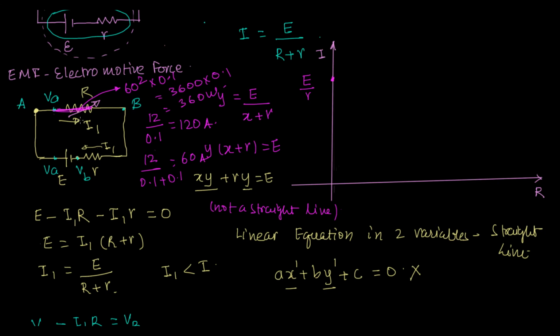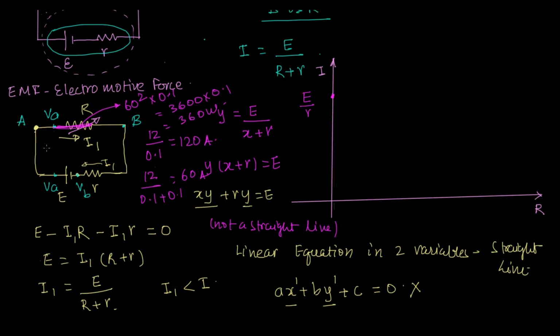So you'll find that the strip has become hot. And if the strip was not that thick, or its surface area is less, or maybe it's a wire, then you'll find that it will melt. It will not be able to handle that much power. And it's good that it melts, otherwise it will burn the whole battery, because this battery is not meant to carry currents of the order of 60 amperes.